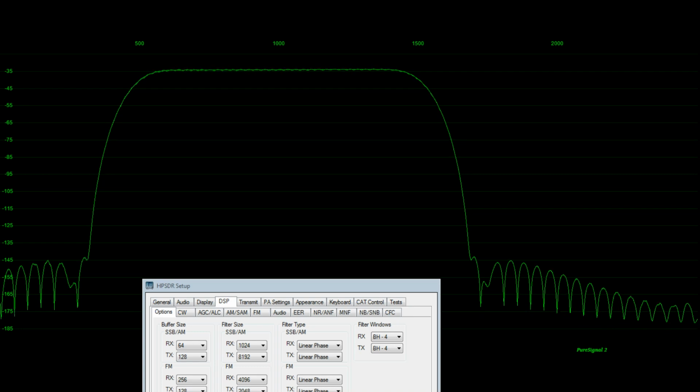Now, this waveform here I generated was just arbitrary. I felt that it would be easy to visualize and fill up the screen in a nice way. It's a 1000 Hertz filter, 1000 Hertz wide. This is generated by simply tapping your variable 1 tab in your receiver filter combinations anybody has available to them on the main skin. You then have a low and a high, and I just typed in 500 and then the high 1500 for a total of 1000 Hertz wide. And that's what we're seeing here as things generate.